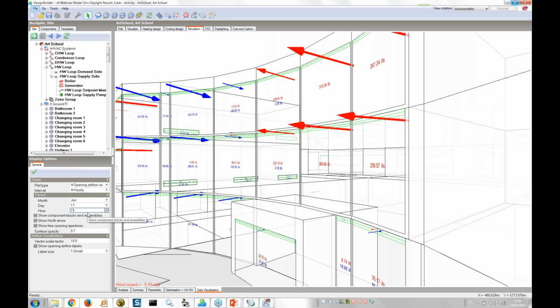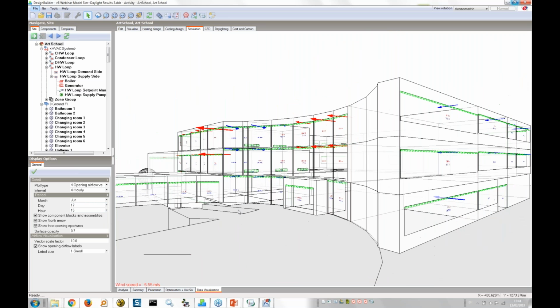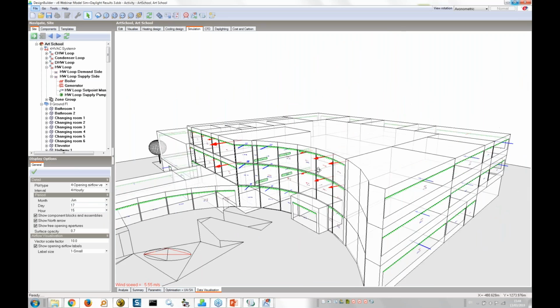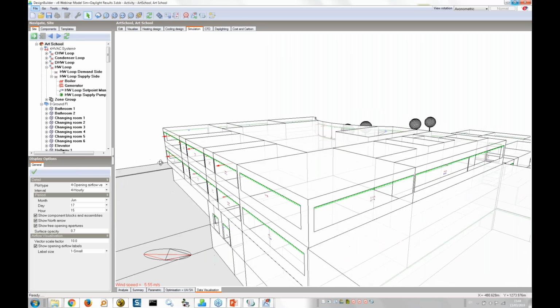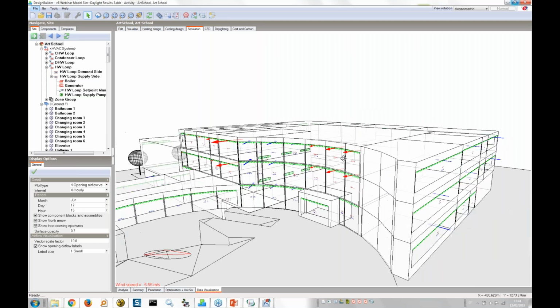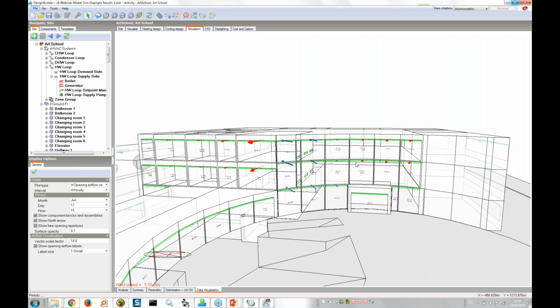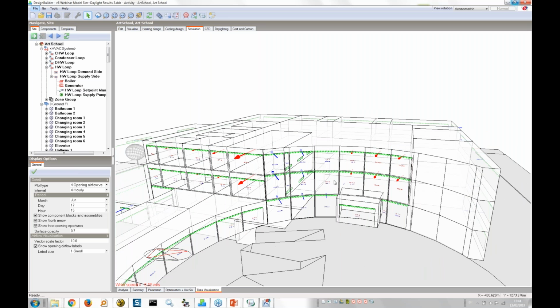Note that generating surface and opening outputs like this creates lots of data, so it can significantly slow down simulations. Custom outputs should generally only really be used for small models or for QA testing larger models. For large models, it is advisable to switch this option off unless you're QA testing.